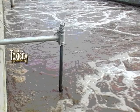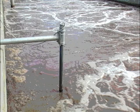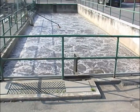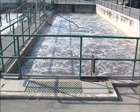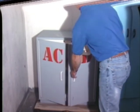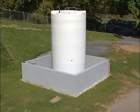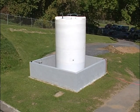Factor number 8, toxicity. Nitrifying organisms are more sensitive to toxic materials when compared to other organisms in the treatment process. Nitrification can be interrupted by the presence of toxic compounds. Effective pre-treatment and sewer use ordinances are a must.